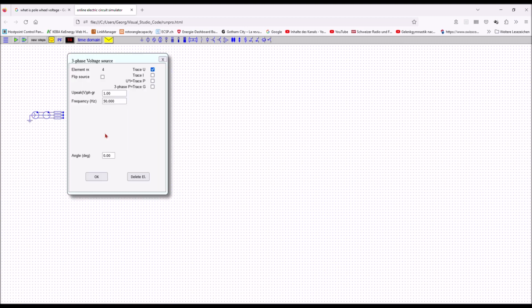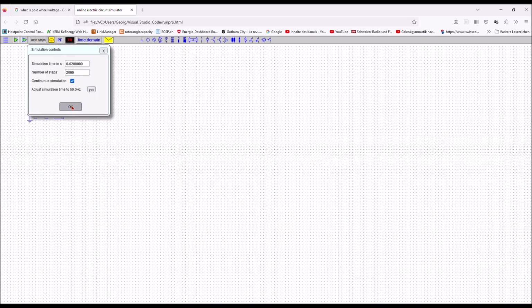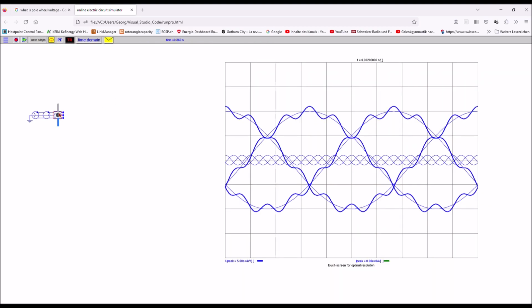This is a very simple one now, so let's just have a resistive load, three-phase ohmic load, and let's see how this looks like. So we would have a 10% harmonic source, voltage source on the source side, 500 Hertz. You can add more of them, of course, if you want, in series. And I would have a relatively high load impedance. And let's check the impact now by running the simulation. Here it is. You can see this is the total harmonics at the load side.